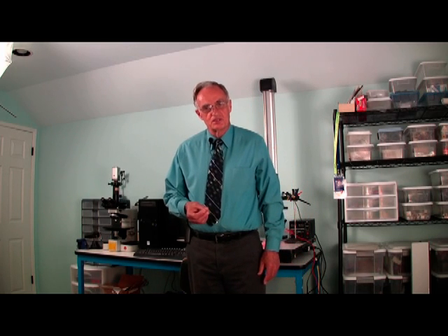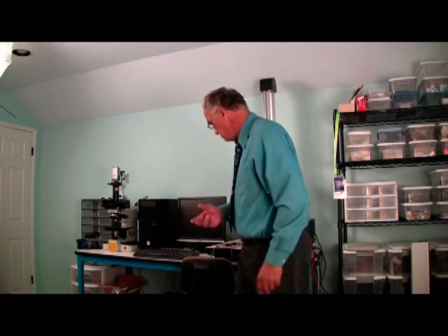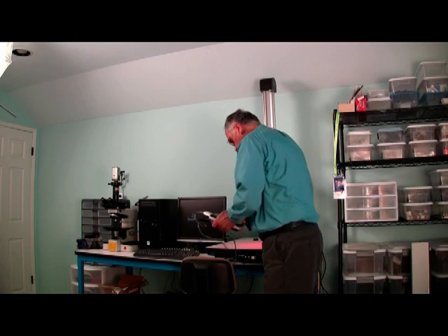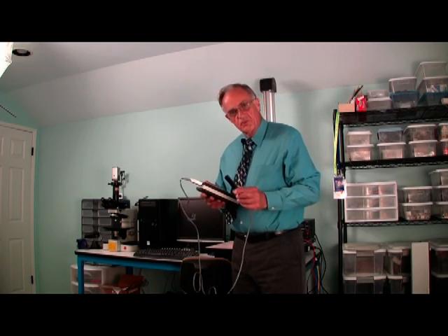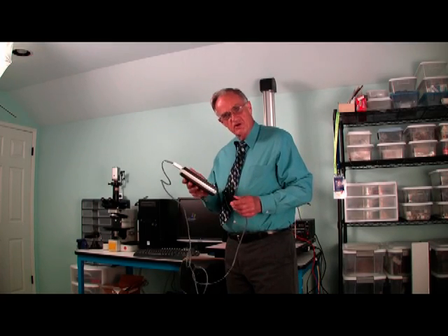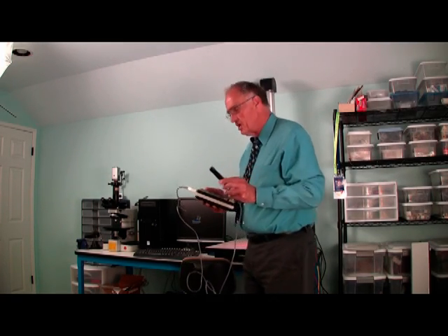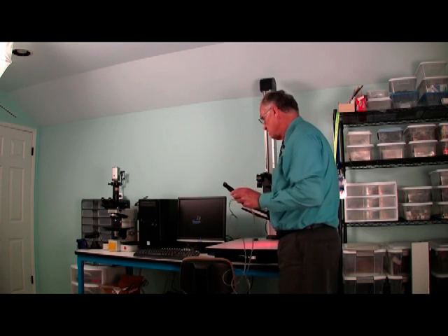We move from benchmarking the image towards benchmarking the illumination. One parameter becomes immediately obvious. We need to benchmark the light level or the intensity of the illumination. There's two ways to do this. The first way involves using a commercial light meter. Now take the light meter and its sensor, which may be part of the light meter or it may be a separate probe, and put that sensor in the middle of the field of view.